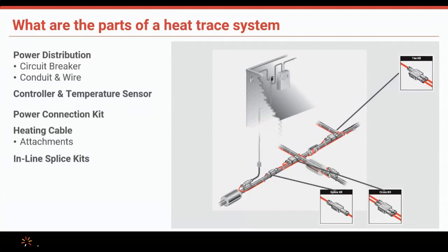In some cases, T connections aren't the right option. I will say that if you're looking at a diagram that shows a long pipe, and then you might have a short 5-foot T segment, and this is just a freeze protection application, instead of putting an expensive T connection there, my design preference is really just to double the amount of heat trace cable that would go along that T and come back to your main and then continue on the pipe as you go. So again, as you're looking through diagrams, keep that in mind. If you don't need to have expensive Ts and man hours and everything else, that's always our preference, to look at the best solution.